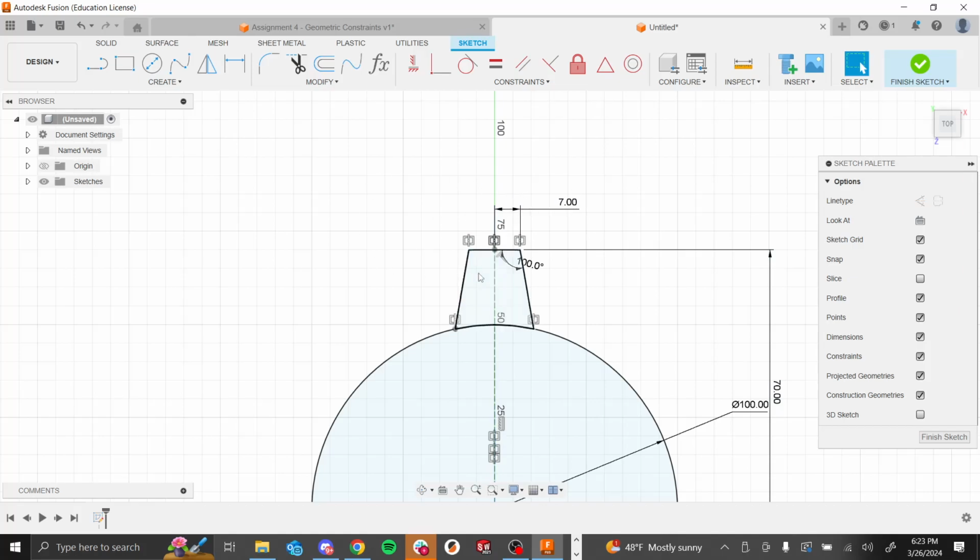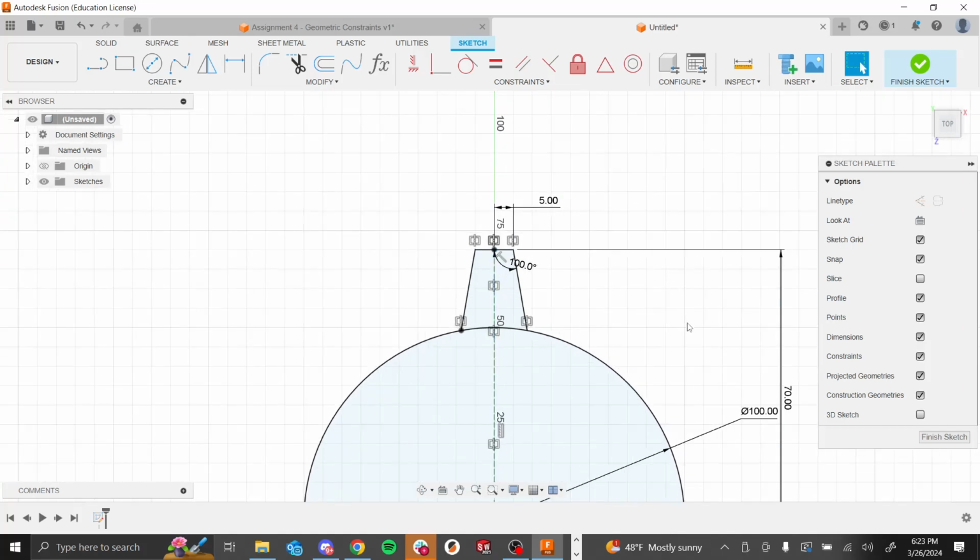And again, as proof that this is really nice, we can modify these parameters on the original side of the sketch we made, and you can see if I change this to 5, both of them change, right? These lines over here are defined by these dimensional constraints that I have over here. So it's super nice for when you want to go back to edit things. I can just change one number or a couple numbers and everything will change along with it.